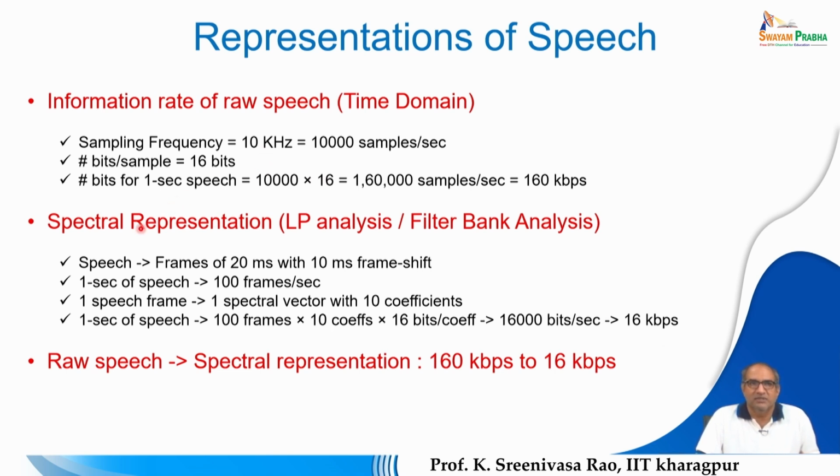And suppose the same signal we can also represent in the spectral domain. So for representing speech in the spectral domain, what to do? We have to apply either the Fourier transform, or we have to perform the LP analysis, or we can perform the filter bank analysis. So likewise, there are various ways we can convert the time domain signal into the frequency domain,